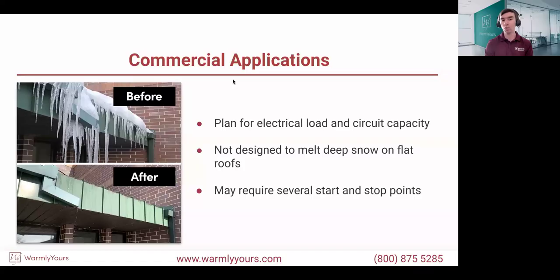For metal roofs, you definitely would want to go with a self-regulating product, and in the quoting process, indicate that it's a metal roof, indicate what seam spacing it is, and of course all the other additional details that we covered, like an overhang. All these components give us the proper way to get that designed.